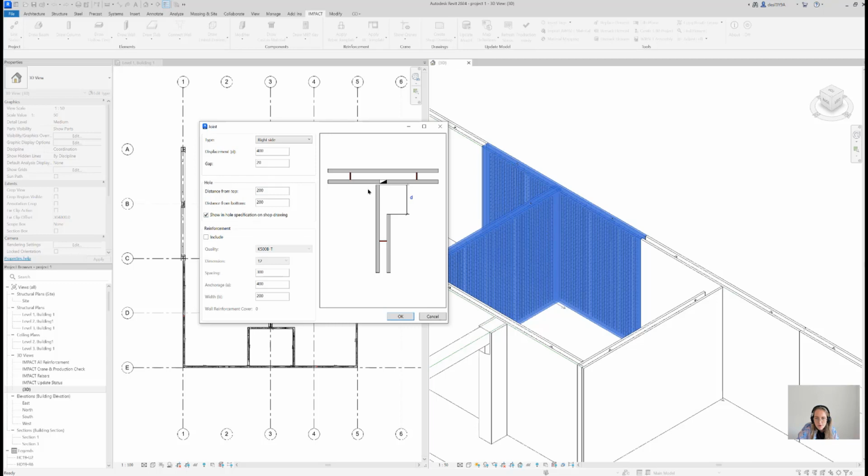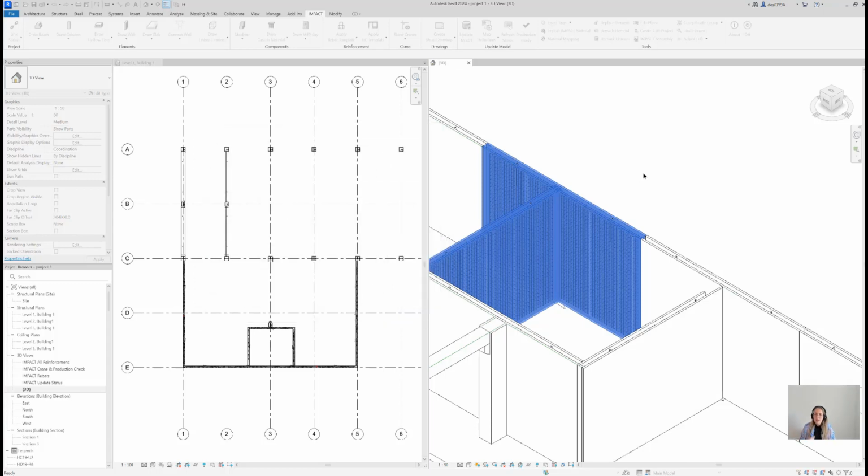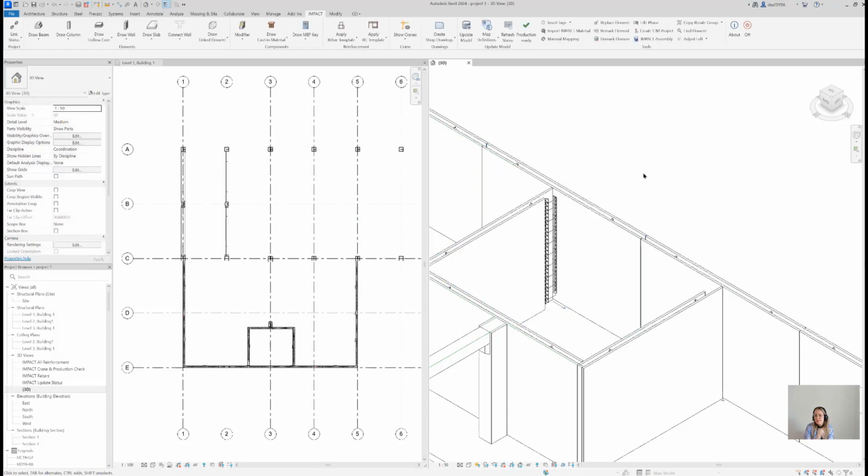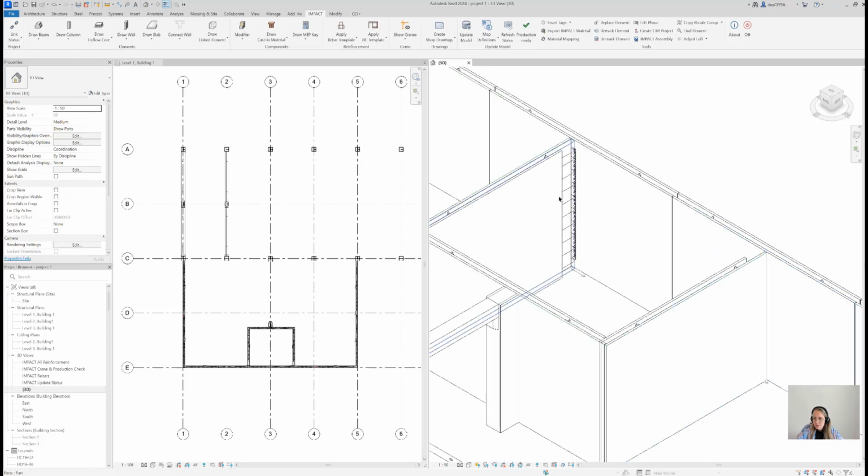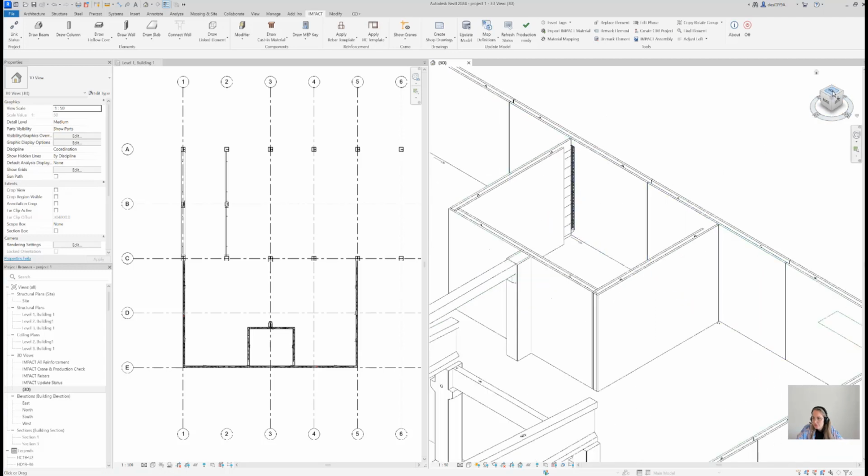This time I want to show the hole in the shop drawing. You see some settings go already now from the modeling to the shop drawing creation. I want reinforcement, and here I think it was 600, and what did we say here? 150. Yeah, let's try with that. Press OK, and Impact is doing the hard work for us. Adjusting the components, and here it is. We have two T connections solved in a couple of seconds. So that's great, that's awesome.